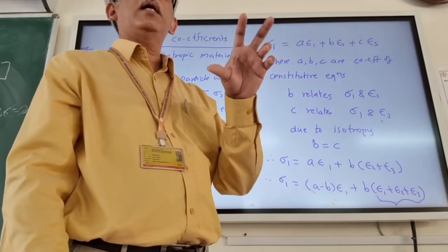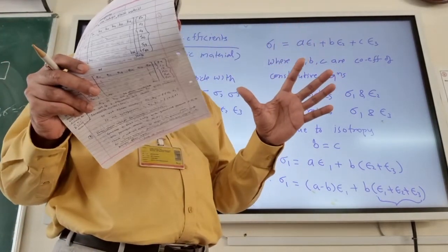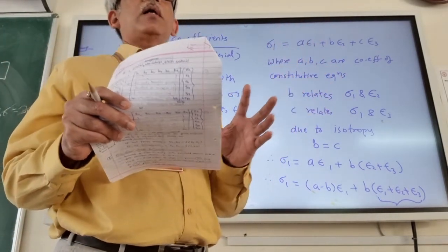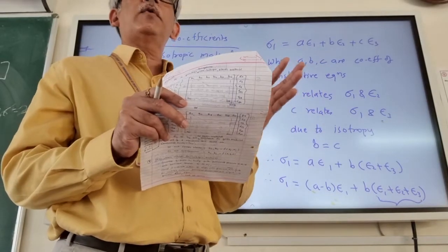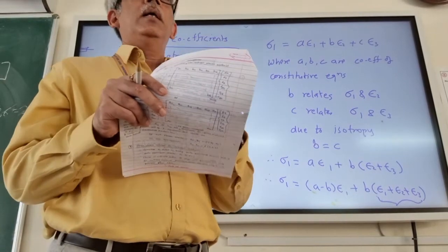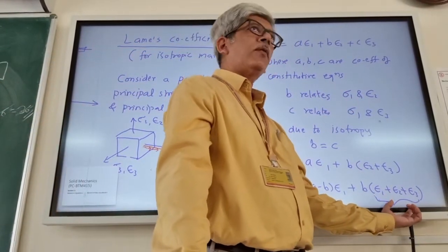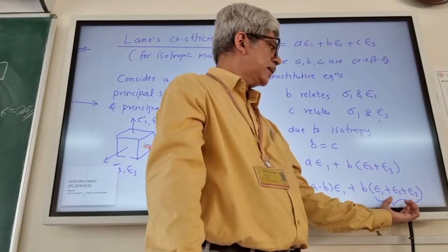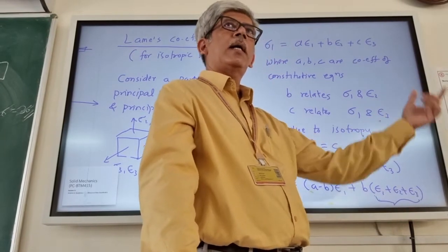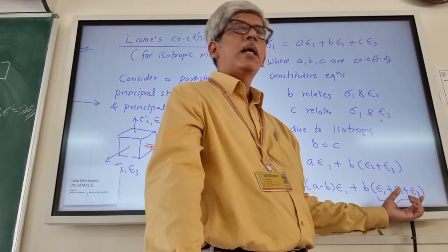In that particular theory, it is assumed that whatever failure occurs, it occurs only because of the distortion of the material, and whatever volumetric expansion or contraction is happening doesn't lead to the failure. So this particular quantity, the volumetric strain, is something useful in that kind of analysis and in some other calculations of solid mechanics as well.